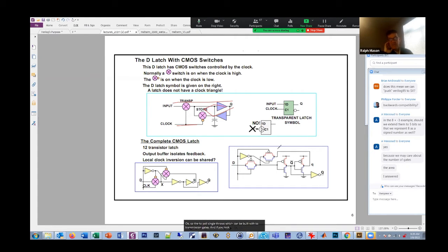And if you look at that physically, it looks something like this on the bottom. We have transmission gate. So this transmission gate here is that one, right? The first one. And then we have two inverters. So we're going inverter, inverter. I just put them in series here, and it comes back. It goes through this transmission gate, which is this one. And it feeds back to this node. So this little node here, you can call it X if you want. The X node is right here.